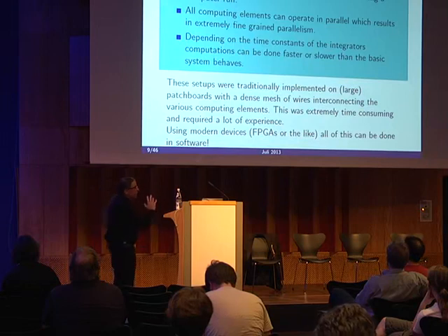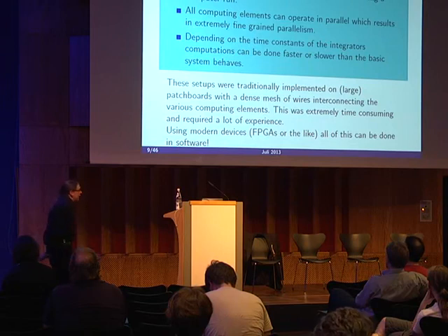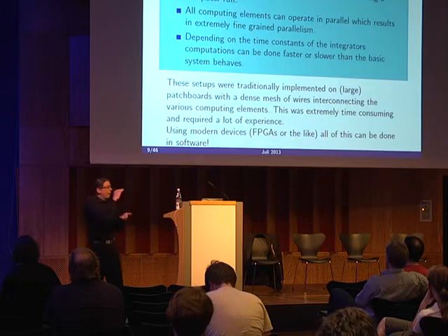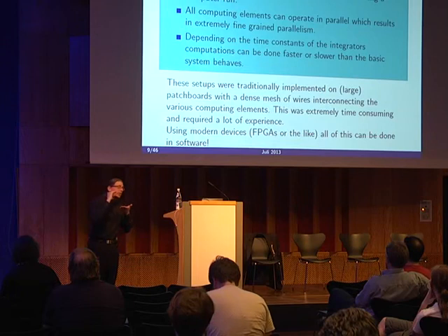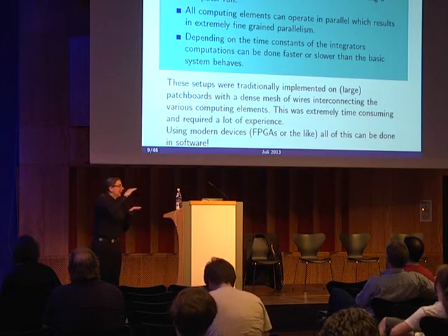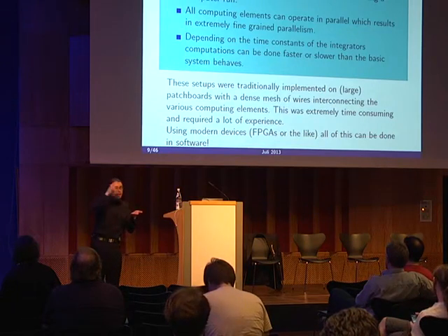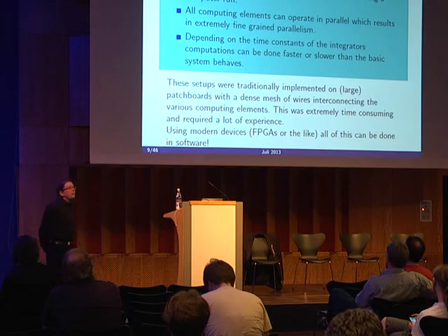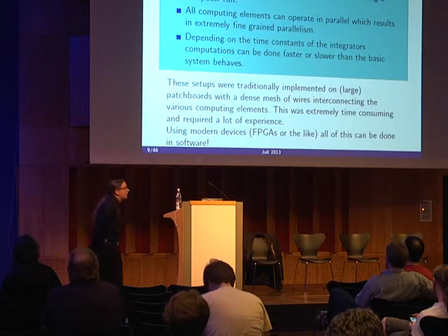There's much more to it. The basic problem in programming analog computers is called scaling. A traditional electronic analog computer has a problem. It only has values between, for example, plus minus 10 volts. So you have to squeeze your variables into this area of values which can be used in the calculation. This makes solving stiff differential equations and the like very, very hard on a traditional analog computer. But using modern technologies could make this problem much easier.